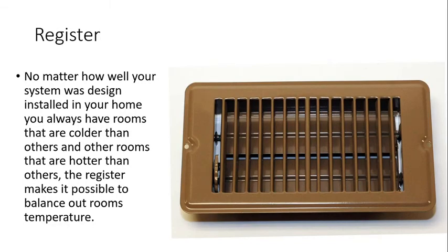Registers. No matter how well your system was designed or installed in your home, you will always have rooms that are either too cold or too hot. It's hard to get the ductwork designed perfectly. Tree shade changes, temperatures change outside. It's hard to make it work. That's why these registers were developed, where they can be opened and closed. These louvers can change their position.